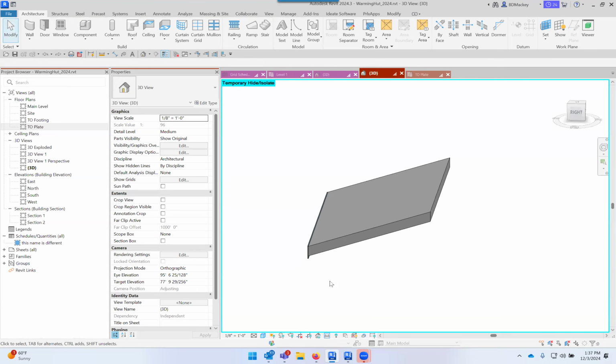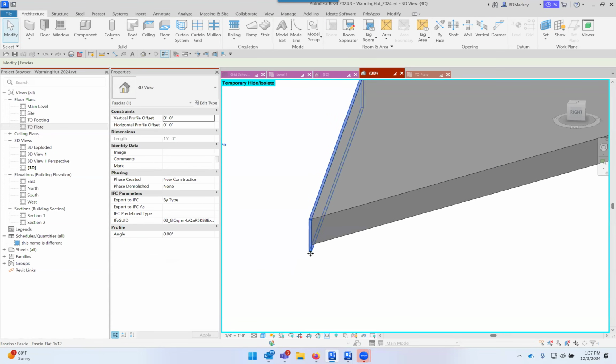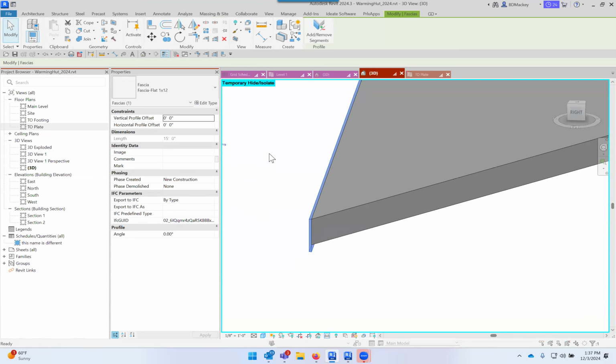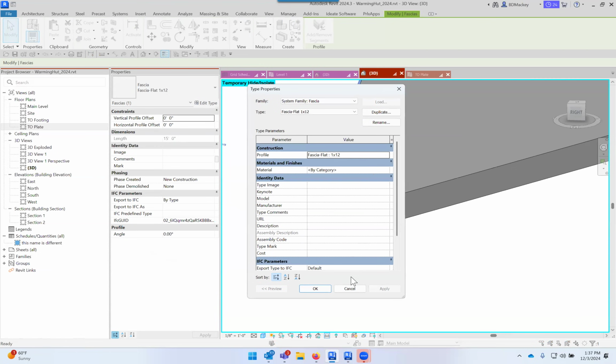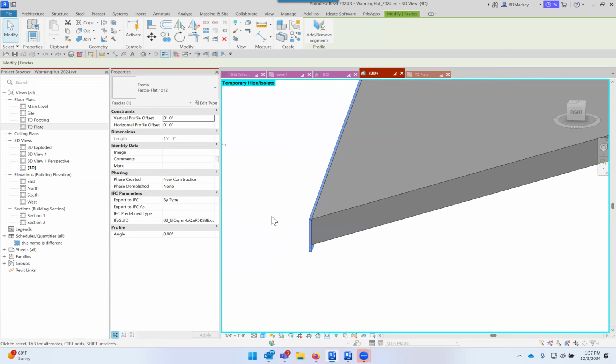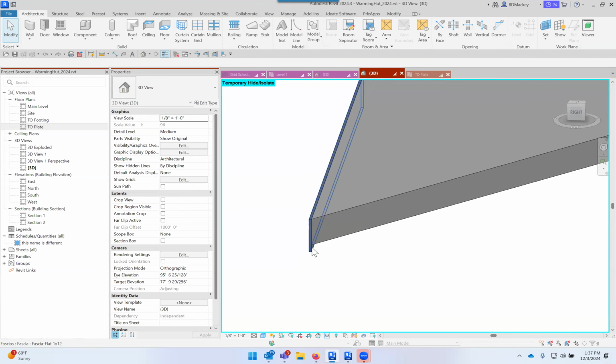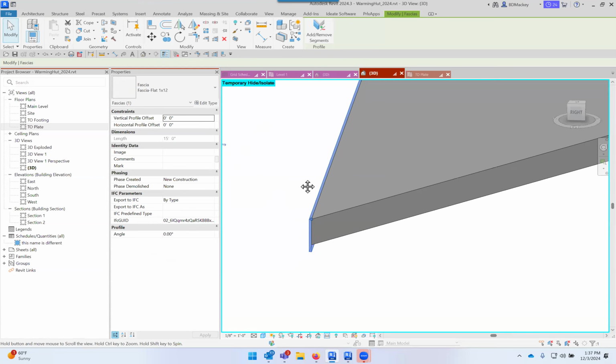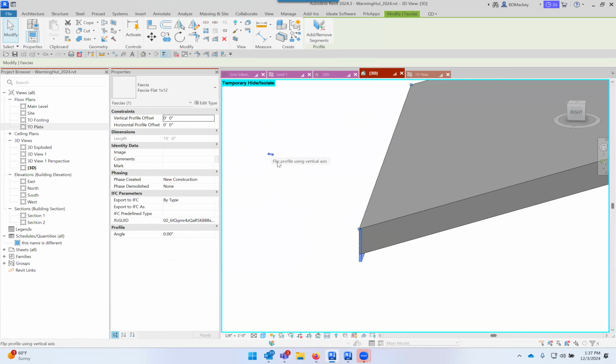Is there a problem mirroring the fascia? When you do a fascia, you have the capability in its type properties. No, you're right. With fascias, you don't. I hate the inconsistency in Revit. On some of the sweeps, you can say flip or mirror. Oh, it's this button over here. You can flip it here. It's not in the properties. It's a stupid flip toggle.